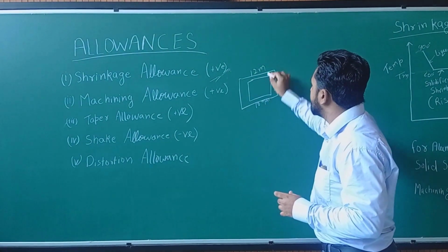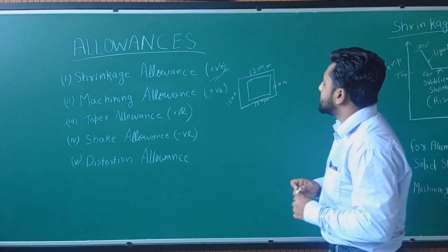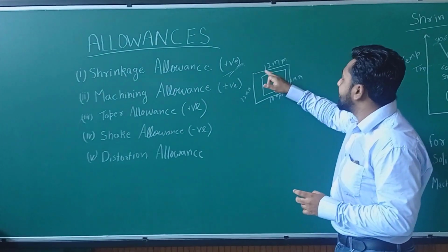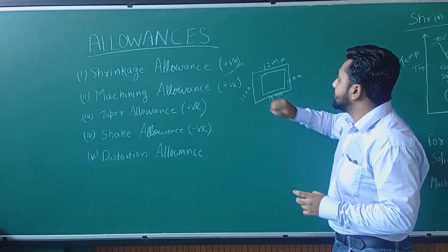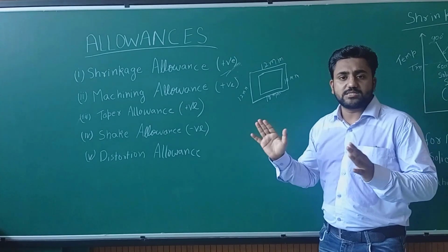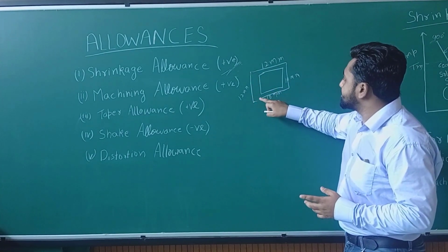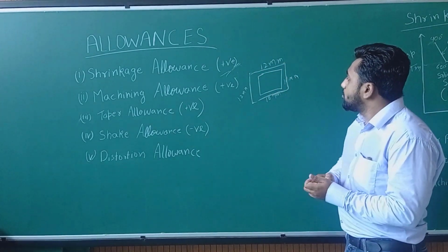12 mm by 12 mm, so that when we do the casting, there will be a lot of defects at the surface at the end. After that we will do the machining, like milling, facing or turning. There are various machining processes, and polishing. After doing that, we will eliminate this extra part, and at the end we will get 10 by 10 mm.